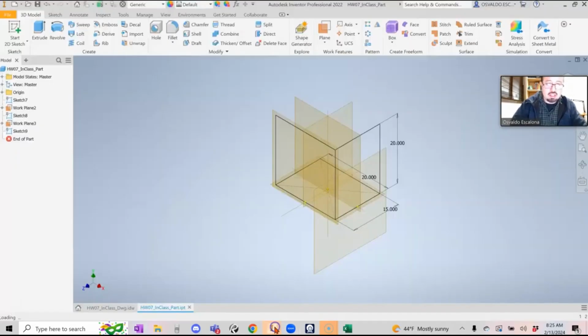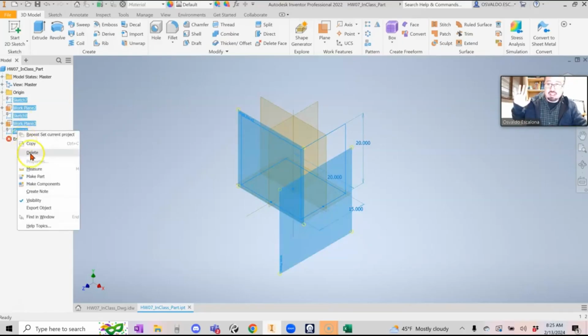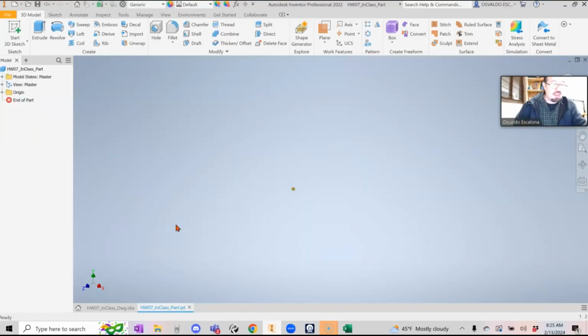The zoom direction is, that's when you notice there is a bunch of things. Probably should clean up your template. I want to erase all of this that's in here because that's kind of how it's supposed to look. So I'm going to click on the first, click on shift and then click on the last one, then deselect the shift, right click, and delete. Okay. Double clicking your middle mouse button centers the view.